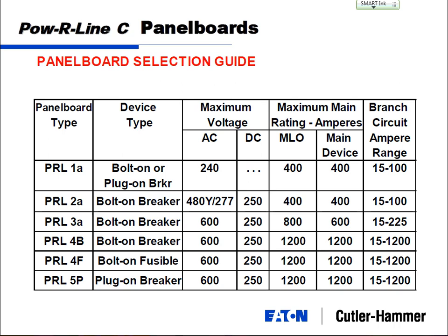Now, for the larger circuit breakers, you still have the option of having a thermomagnetic trip unit in there, but in addition to the thermomagnetic trip unit, you can also get what they call a solid state trip unit. Okay, this one's a solid state trip unit. I don't think it matches this circuit breaker, but basically you can just rip out this one here and put this in here.